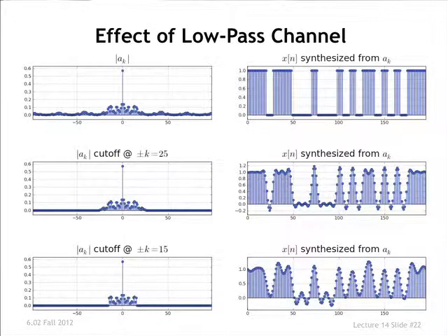In the first case, everything goes through, there's no distortion, you get the same thing back again. In this case, the channel has a cutoff that ends up zeroing out all spectral content outside of some frequency range. So it's a low-pass channel whose bandwidth is not enough to take the spectral content of what you're feeding across. So what do you expect to happen?